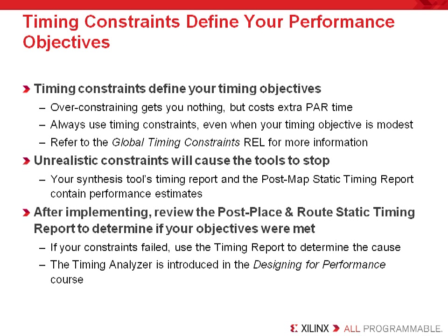Now, timing constraints are going to define your performance objectives. As I mentioned before, if you don't use timing constraints, the tools basically assume you don't care about the timing. Over-constraining your designs gets you nothing, but it costs extra par time. As we tell people, the key thing is to define timing constraints that are going to define your actual timing objectives. And of course, if they're unrealistic, that means you really didn't do a timing estimate to begin with, and so you really don't know what you're in for.